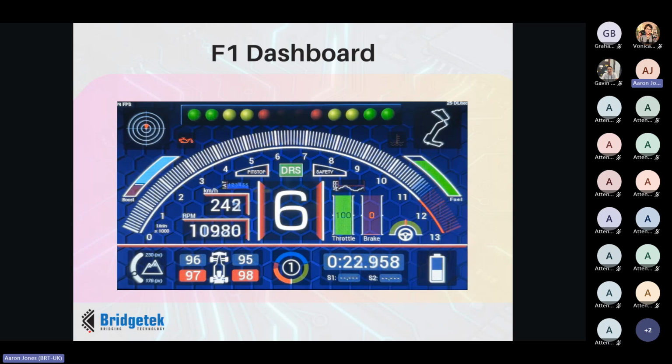Instead of the MCU worrying about how to draw each gauge or fill every line, we send object-oriented commands and leave the calculations and rendering for the position of these items and their fills, etc. up to Eve. This makes it an efficient way to drive highly active displays that need continuous updates.